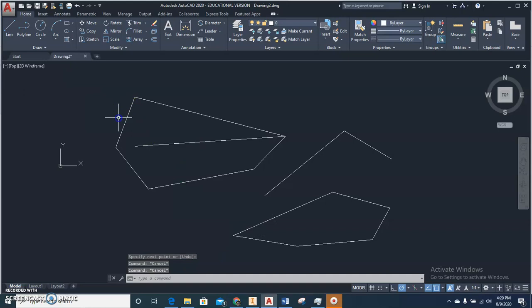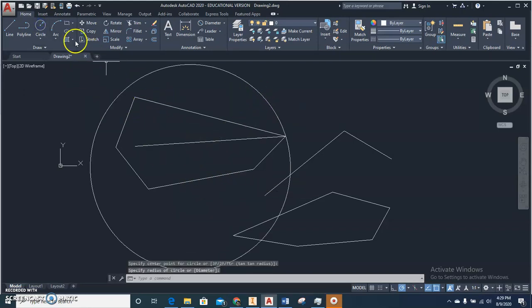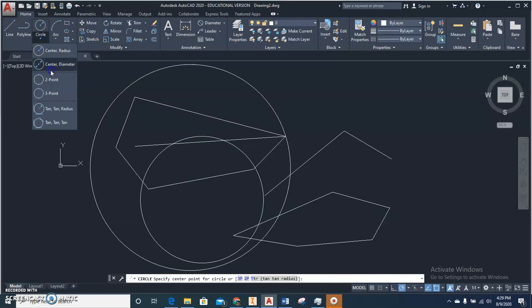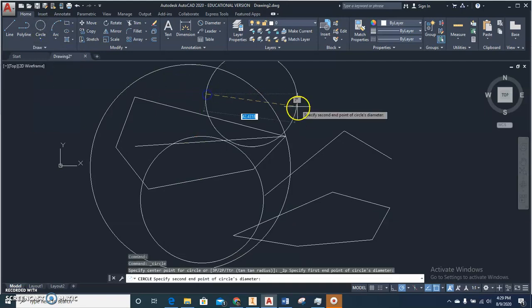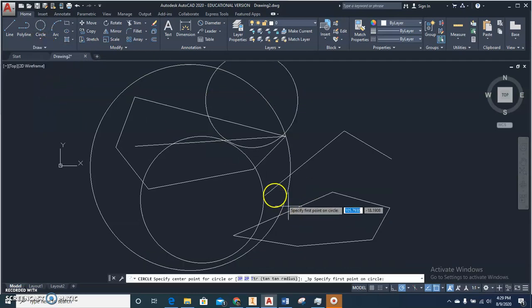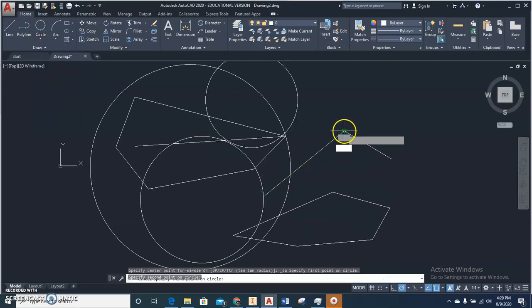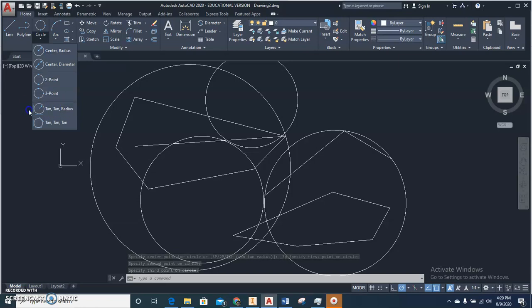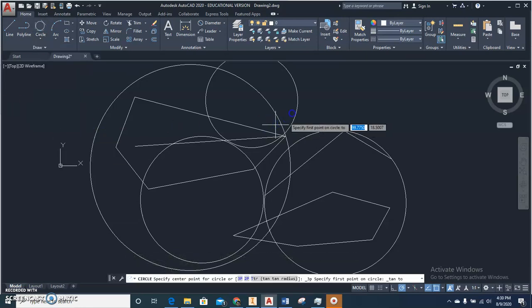It's a cool feature. Okay, circles. Let's draw some circles. Circles default to diameter. There are different types. There's 2-point, where you go from one point to the next. There's 3-point, and let's see if I can get a little creative here. Click, click, click. It attaches those points on the circle. There's tangent radius. You're going to use this a lot, but you have to type in something for it, so don't worry about it right now. I can probably do the tan.